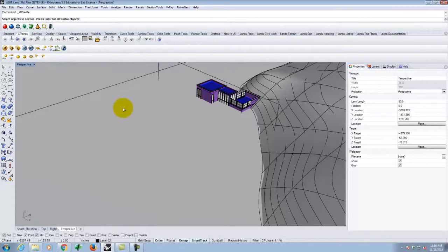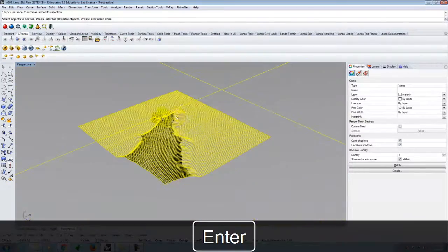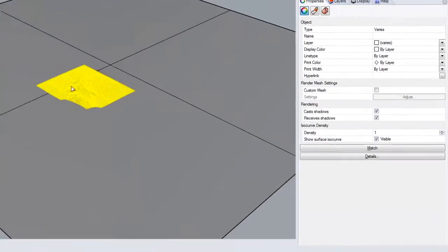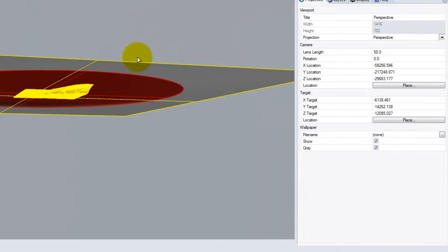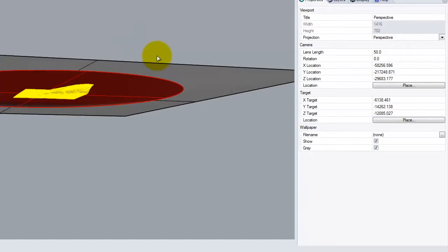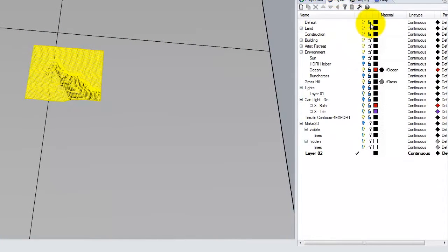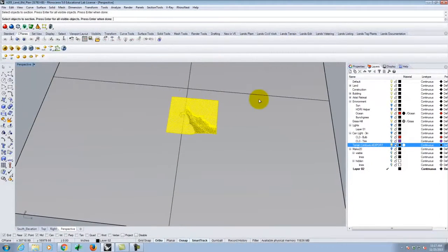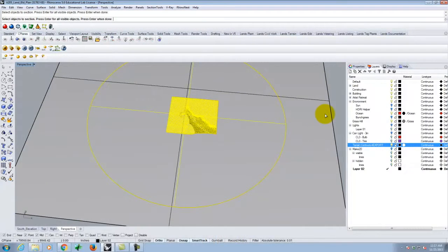I'm going to select objects, which will be all except for that big plane. I don't need that, so I'll hold down Control and deselect the plane. I should probably select, well, the ocean doesn't really matter because I'm not cutting through it anyway. Okay, so I have all those objects selected. Let me look at my layers here. Oh, looks like I have some locked layers, so let me go ahead and unlock layers, which is probably why I didn't get everything selected. So let me go back and say all, and then we'll deselect just the big plane.